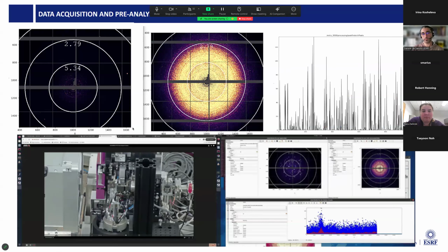So, a bit on data acquisition and data analysis. As I said, we operate with the Jungfrau 4M, which is operated through an ESRF-developed data acquisition pipeline and backend called Lima 2. With Lima 2, we do on-the-fly geometrical correction of the images and pedestal correction, because Jungfrau, being an automatic gain-switching integrating detector, needs the pedestal corrected for the 3 different gain levels.